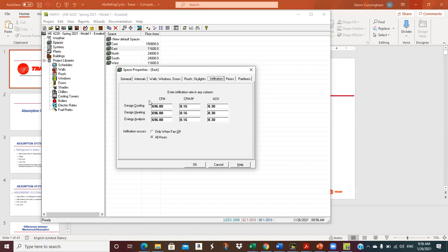Now, good old Brown Hall, man, the wind blows, you go over there and stand by those windows and you can feel it coming through, because they're single pane and they're, what, 40 or 50 years old, and they leak like a sieve. And in the hallway, how many air changes per hour do you think we get coming in those main doors and out on the ends? Oh, probably 3 or 4 or 5, especially on a windy day. You get lots of air change. So, it takes some time to get used to air changes.